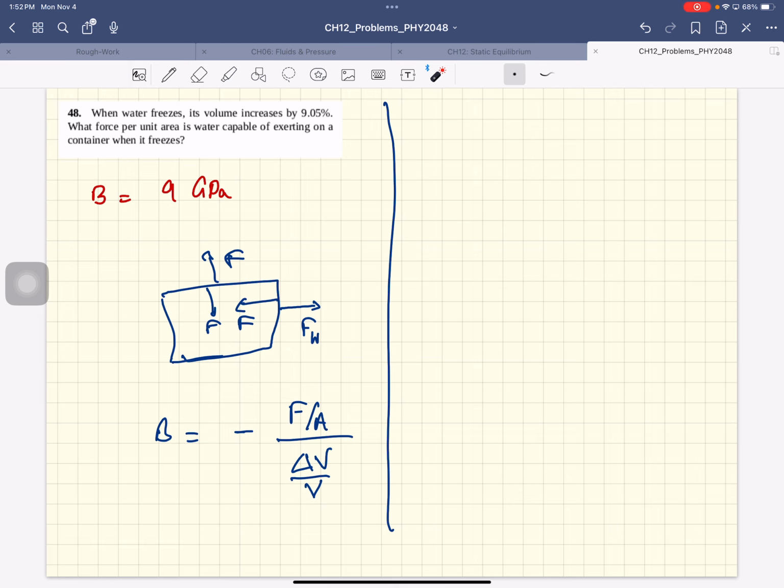So a suspender rod of a suspension bridge is 25 meters long, which is roughly the width of this room. If the rod is made of steel, what must its diameter be so that it does not stretch more than 1 centimeter? So you put a load, the less you want the rod to stretch, the thicker you want it to be, right? And so what are you trying to do?